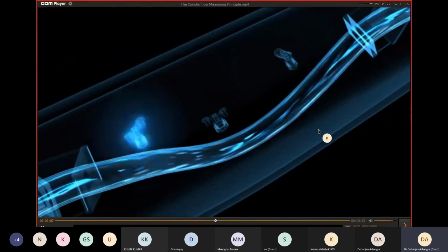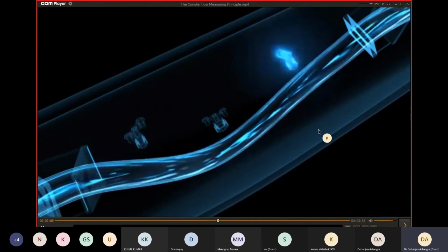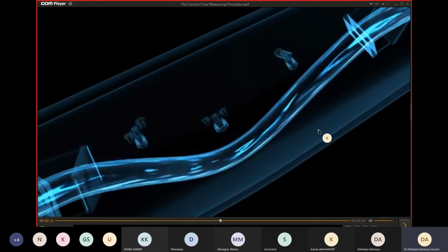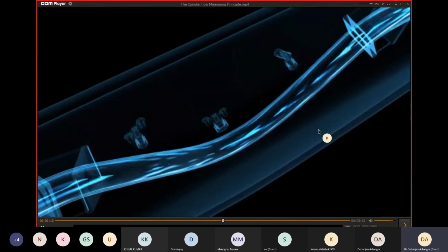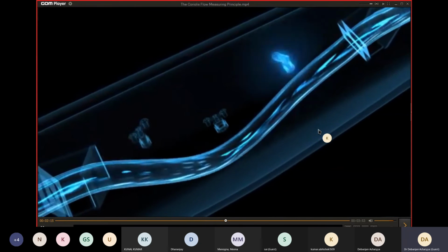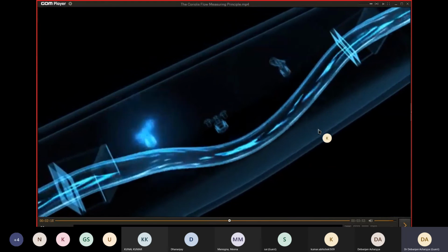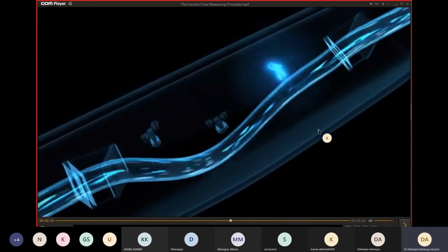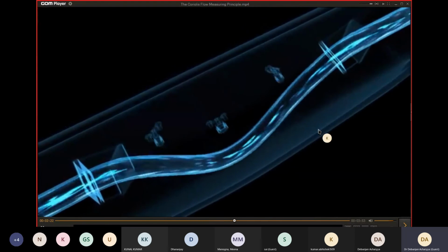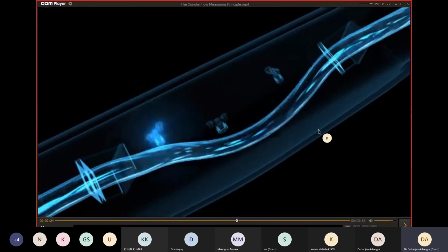This is known as the phase shift, and is a direct measure of how much liquid or gas is currently flowing through the pipe. The higher the flow velocity, and thus the total flow, the greater the deflection of the oscillating measuring tube.